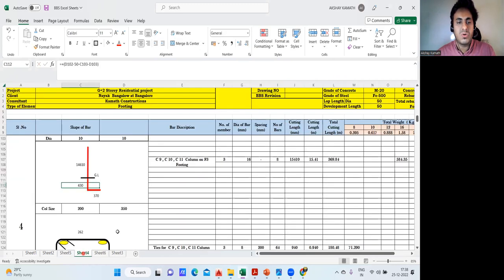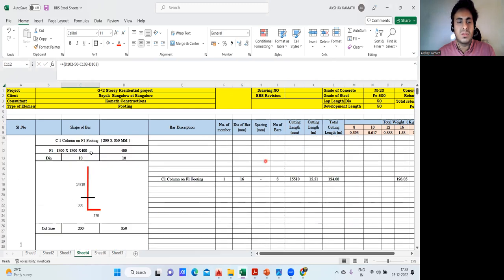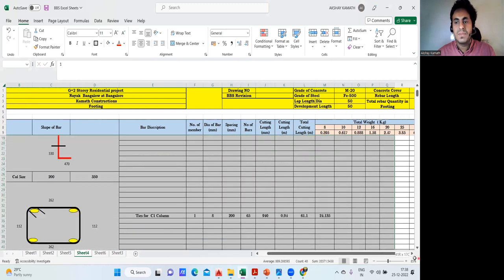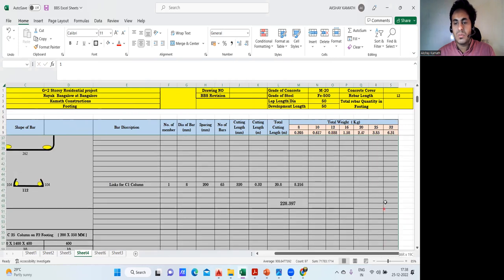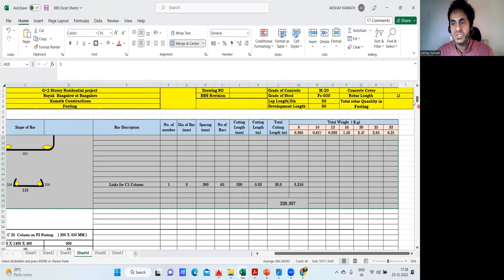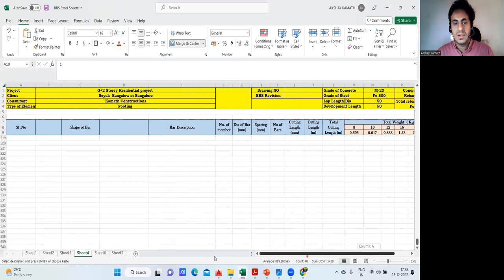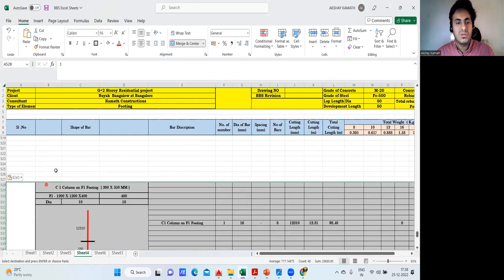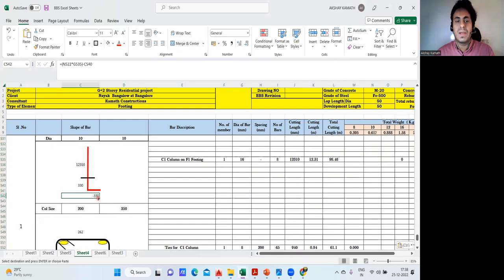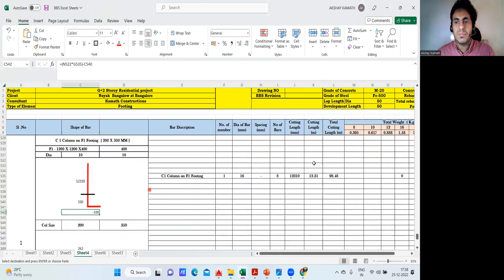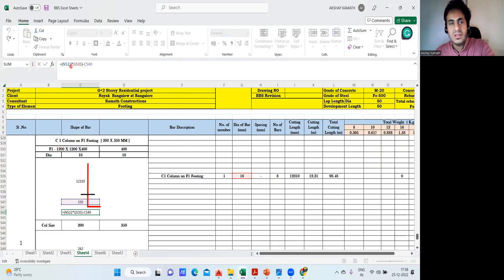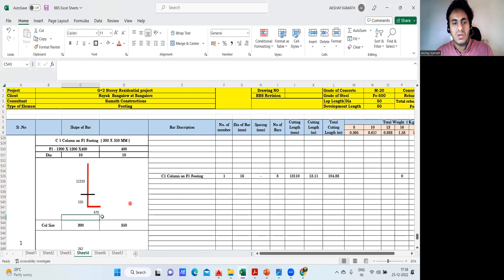What I want to convey is, suppose you're copying something, let us say I copied this, Control C, and I'll paste it here, Control V. So what will happen? You see, every time you do that, you get a minus here. The reason is this is 50 into D minus this length, so it takes this value. Just come here, delete this portion, and enter development length 50. Enter. Now it will be all right.